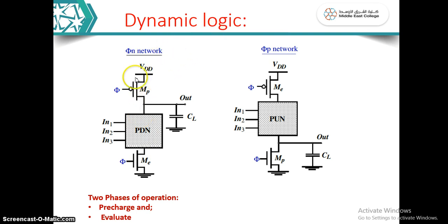In dynamic logic, if we choose only the pull down network, whatever the expression given to you, you have to implement by using the pull down, meaning NMOS network. So by using the NMOS transistors, and these are your primary inputs, whatever you are giving over here, you implement the expression by using NMOS logic, and that logic forms here.